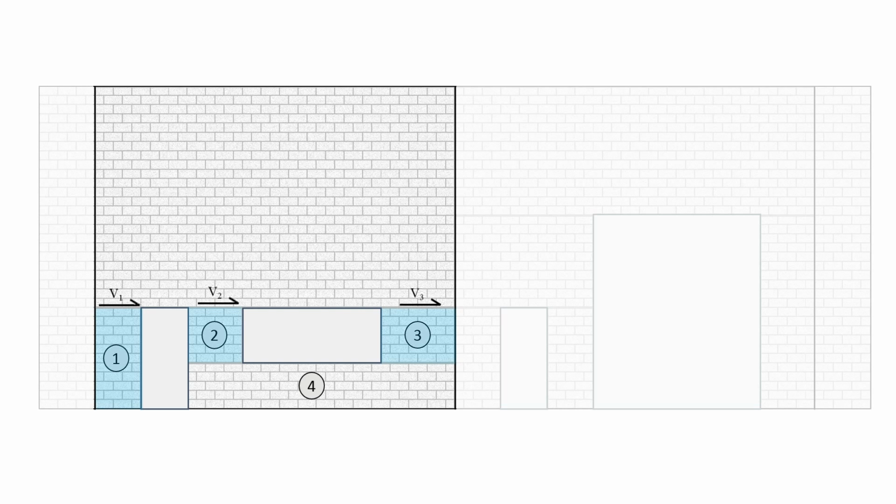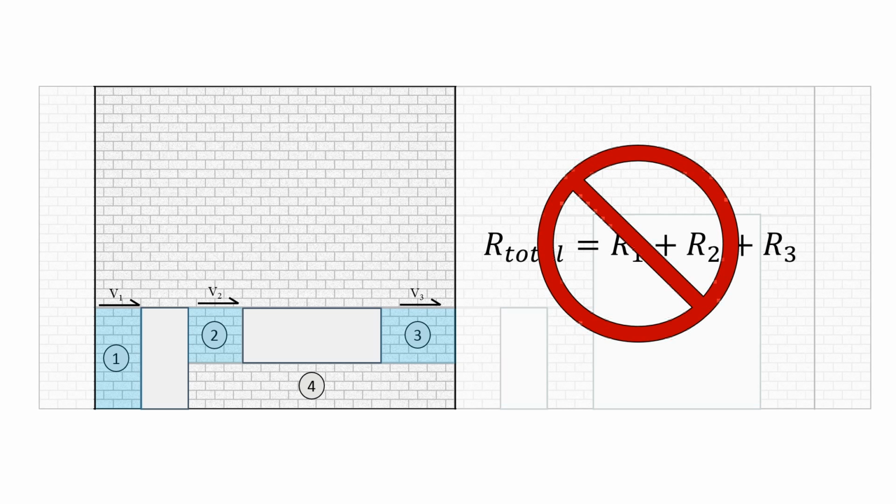Looking at panel 2, we know that whatever load is applied at the top is going to be shared between these 3 piers. Now it would be tempting to simply take the rigidities of pier 1, pier 2, and pier 3, add them together, and look at the ratios, but you would definitely be wrong if you do that, so do not do that. A lot of people do that. Please do not mess that up.